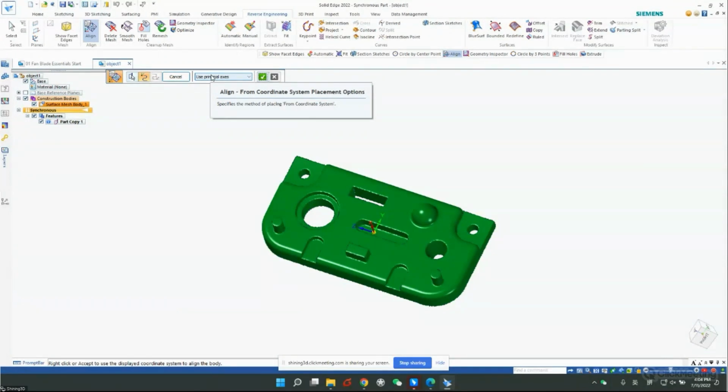That's hard to align. The smooth function, actually, there's some control. You can select how many iterations to do the smooth. The more you do it, of course, you lose more details. And I think it is easier. It's actually easier to align the data in Solid Edge, but it's more accurate in the scan software.